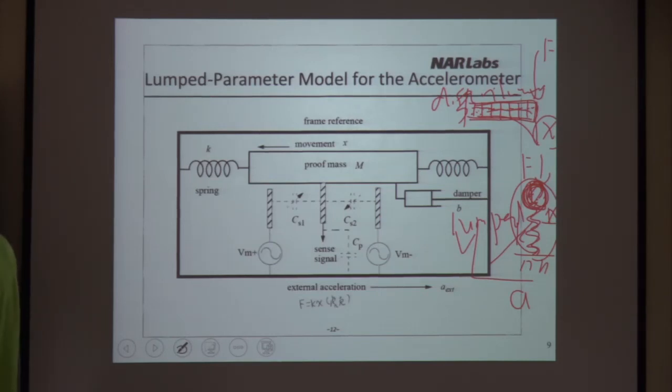You can use theory, mechanics theory. You can apply F, then calculate moment and reaction force, then cut here. Then this is Mx. Mx divided by EI equals curvature.